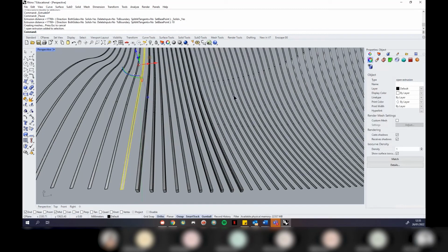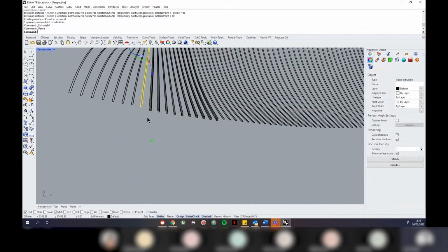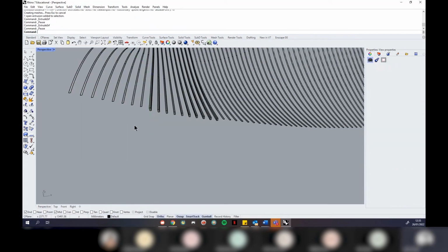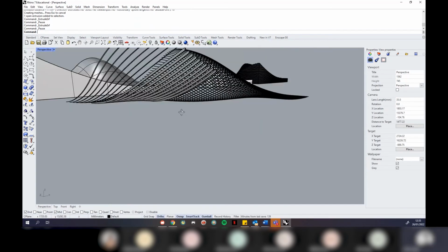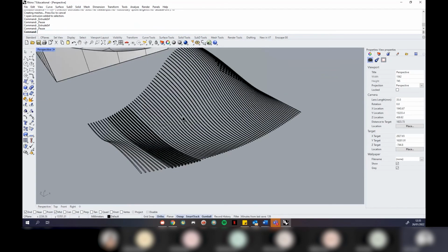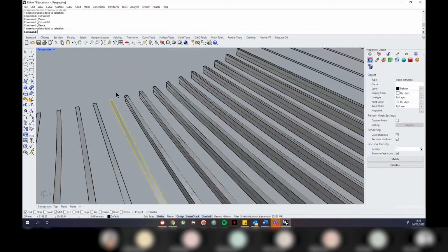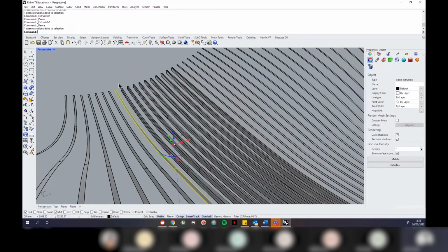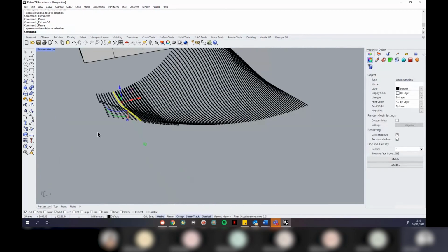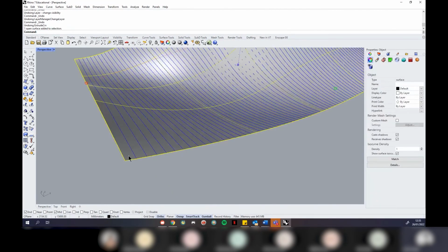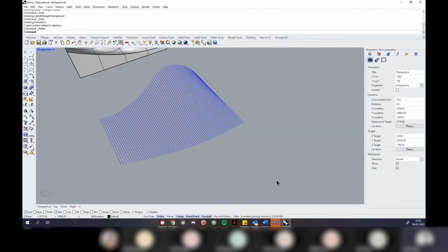Now, I don't know why it didn't want to extrude that one. Why did you not want to extrude? It just does it sometimes. Rhino does work 99% of the time, but occasionally you will get random issues with things. I'm not seeing any issues with the geometry. That should be extruding. If it doesn't like it for any reason, it's just a case of undoing it, go back to the previous step, and just re-offset your stuff. So if I just go back to this stage, for instance,